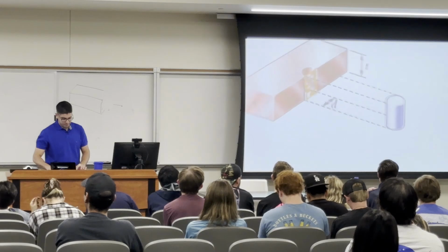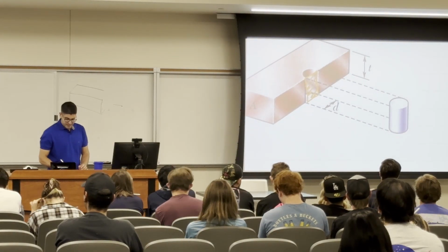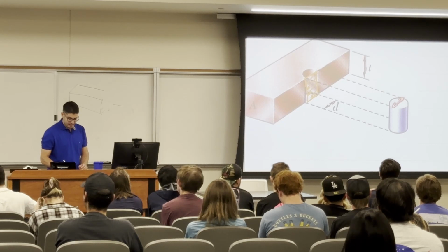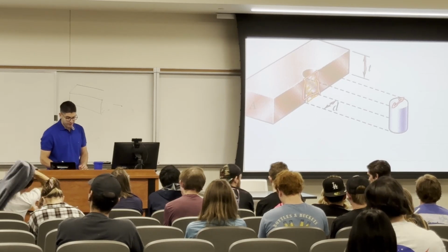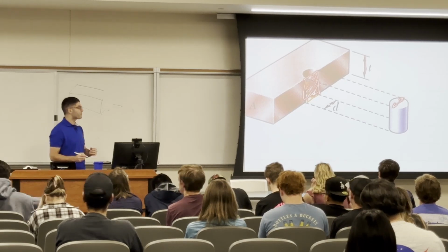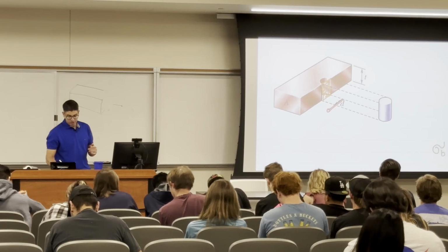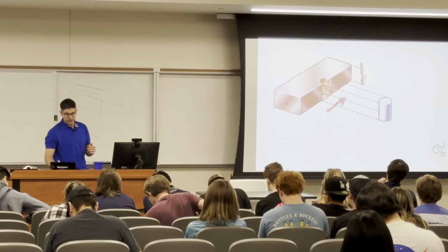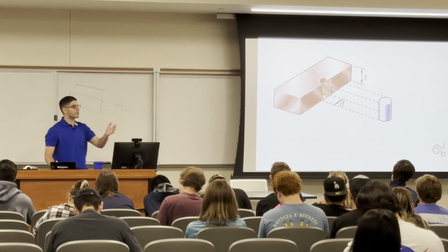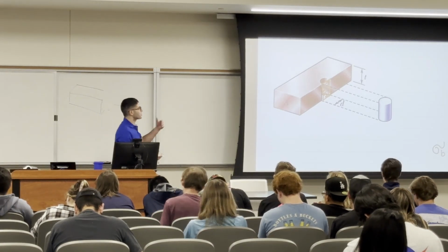Yeah, which is this. I was looking for this. So this is the rod, where D is the diameter and T is the thickness. So this is the projected area that can resist the bearing. So if I want to prevent the bearing failure, I either increase the diameter, or increase the thickness, or increase both. That's how I resist the bearing.